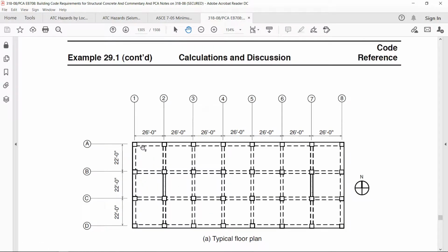In the north-south direction, we can see the concrete special frame with shear walls over here on grid number 2 and on grid number 7. These are the two shear walls. But in the east-west direction, there is no shear wall. The special moment frame system is resisting the lateral load in the east-west direction. So with all this information, I will model this